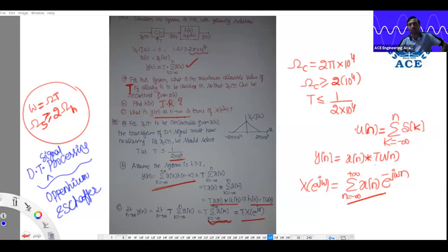We know this is the accumulator. In Z transform also we used the word accumulator. Sigma minus infinity to n xk is the accumulator. That I adjusted as xn convolved with this one, because xn convolved with delta n is xn only. Everyone can recognize this is the unit step sequence. Running summation of impulse we studied as un. So T un is extra. If you compare with the xn convolved hn form, by comparison, hn is simply what? H of n is simply T times un. Okay? Only comparison, sir. Compare with the convolution formula.